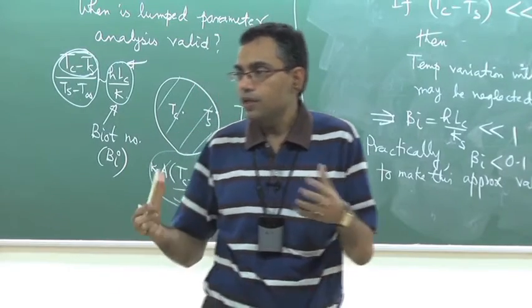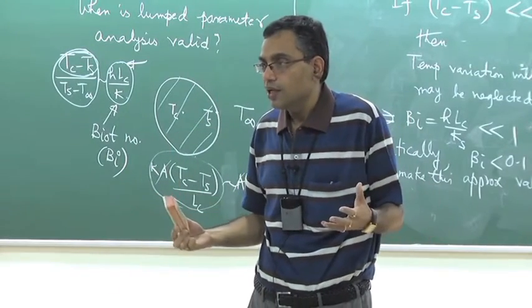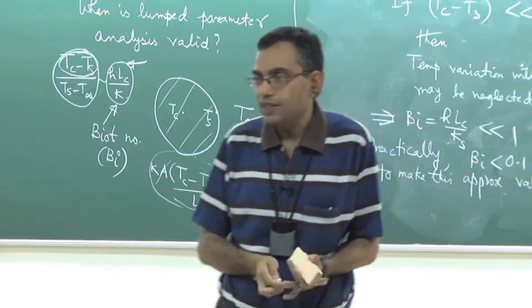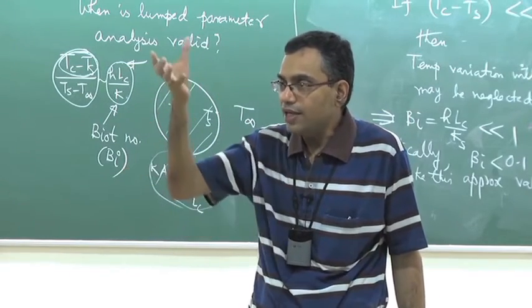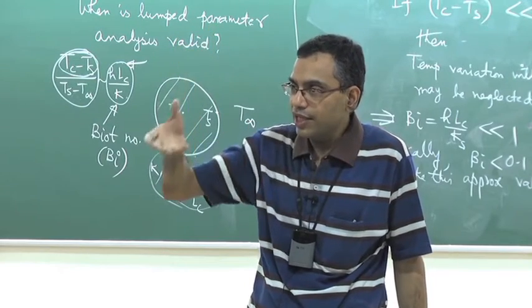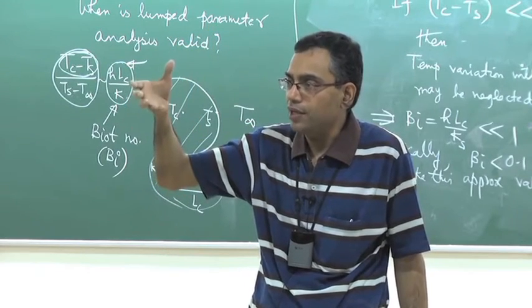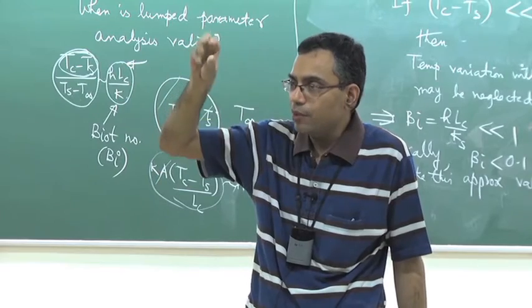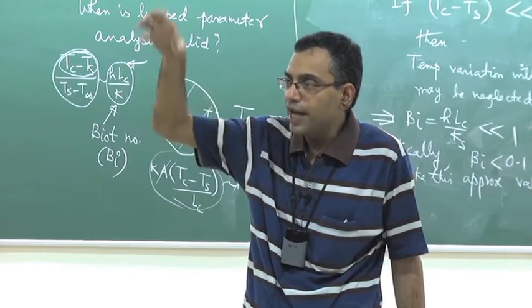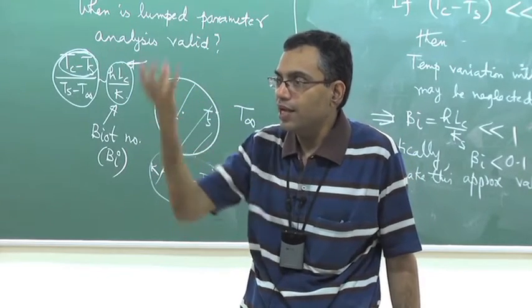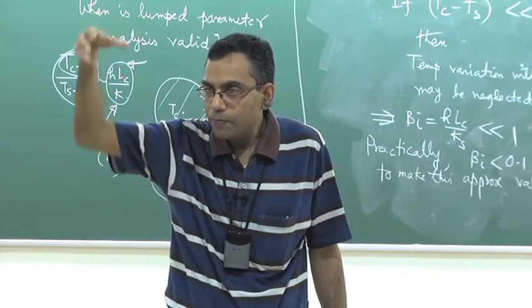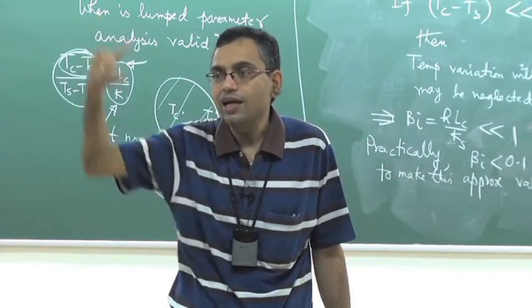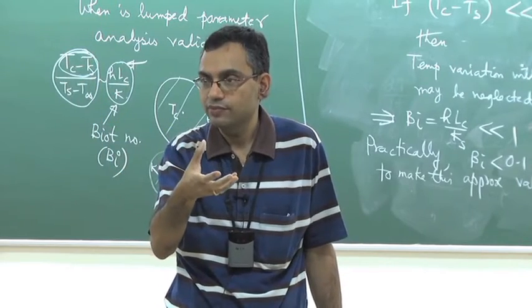So in a casting process, you know that there are shrinkages at various levels, and when there is a shrinkage during solidification, what will happen? There will be a volume that needs to be replenished, and the riser is there as the supply of the molten metal, which will supply to the mold till the entire mold solidifies.